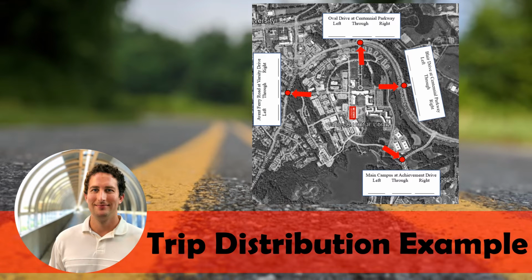This is a trip distribution example, primarily in the context of the four-step project planning process that starts with trip generation. So what trips are being produced or attracted, where they're being distributed, and that's this step, trip distribution. Then modal split, so which mode of transportation are they going to take? And then finally, trip assignment, so assigning those trips by specific modes distributed to their locations on the actual network. In this example, we're focused specifically, though, on trip distribution.